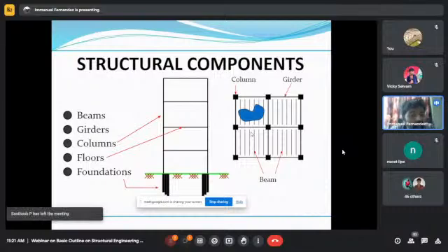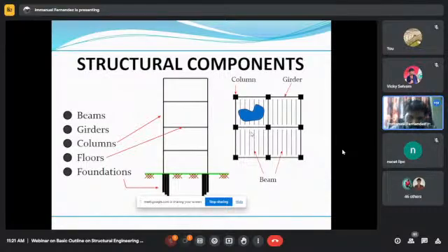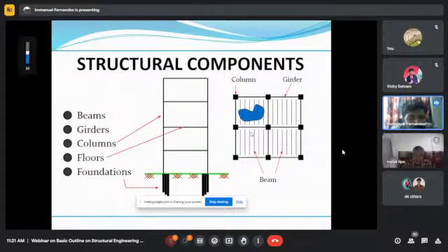And the capacity, how much the soil will carry, will be given by the geotech engineers. Like if it is an open foundation, which is nothing but the foundation without piles. And if we are going for pile foundation, that recommendation also has to come from the geotechnical engineer, that these soils are not adequate for the open foundation. We don't get the bearing capacity, so you have to go for pile foundation. So based on the geotechnical recommendation and the technical document given by the geotechnical team, we decide what type of structures we have to go with, pile or open foundation.